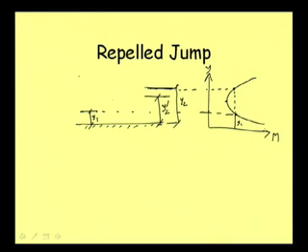So, where will it jump, when we do not have that depth? What will happen in this situation? Then we need to see, if this is y1, and if the tailwater depth needs to become the sequent depth y2, then what will have to be the initial depth.